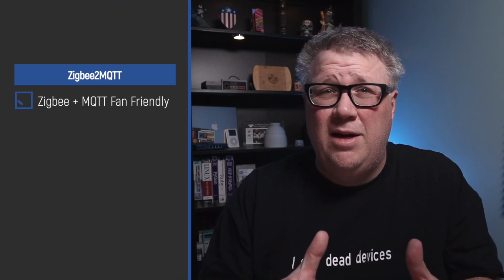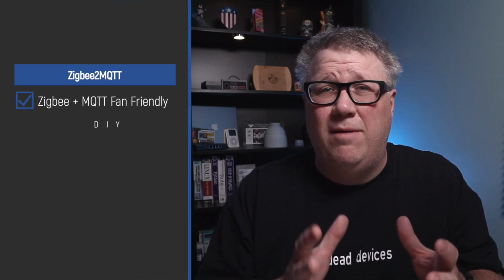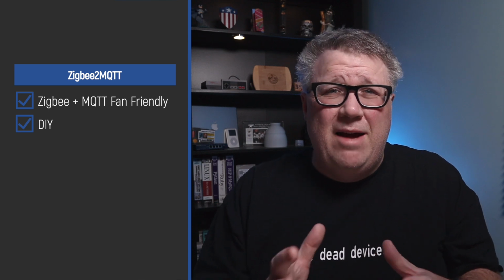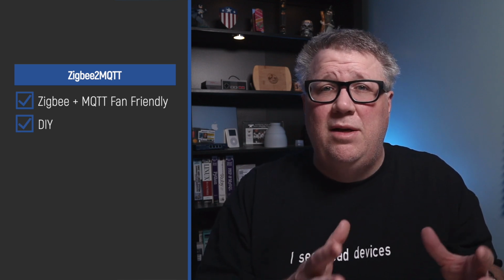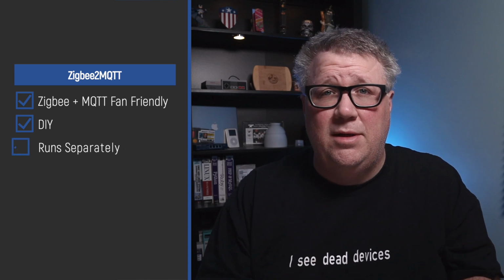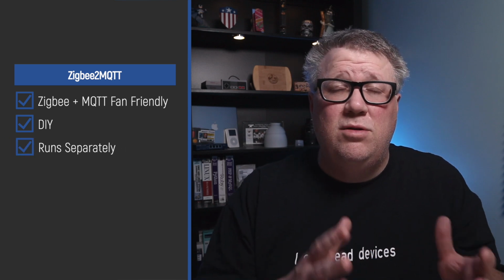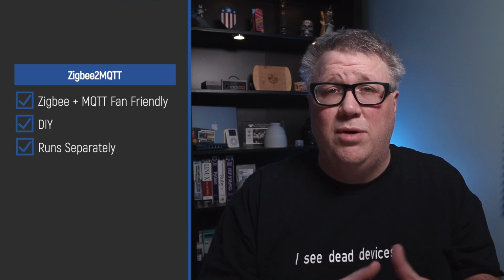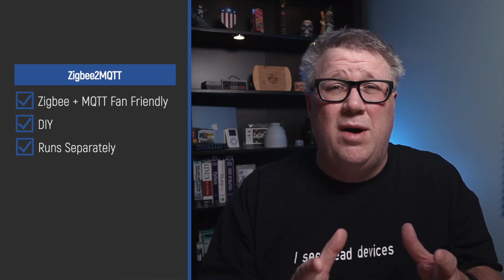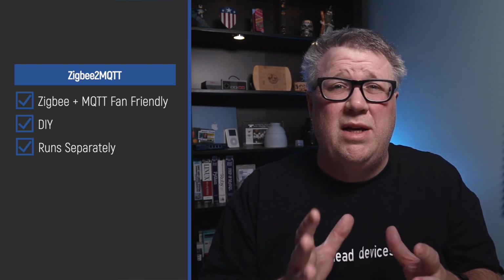Zigbee to MQTT is the path for anyone who loves Zigbee and MQTT, and it's definitely more of a DIY flavored path. But it does have the advantage of separating your Zigbee network from Home Assistant. This means when you restart Home Assistant, your Zigbee network doesn't go down. So as soon as the Home Assistant UI is back up, your Zigbee devices are ready to be used.